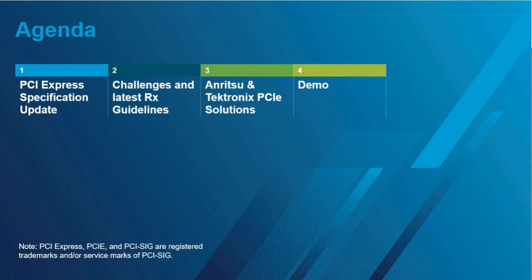For the second agenda item, we will focus on receiver testing at 32 gigatransfers per second. We'll look at different tools and the implications of using a simulation tool versus waveform tool, specifically the impact on calibrating your crosstalk term. We'll look at the meaning of different test points within the channel and how to properly choose your channel. And we'll also discuss tiebreakers. How do you know when you've finally achieved that correct stress die calibration to properly test your receiver?